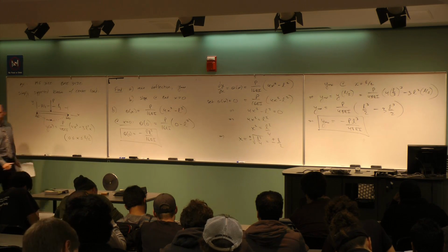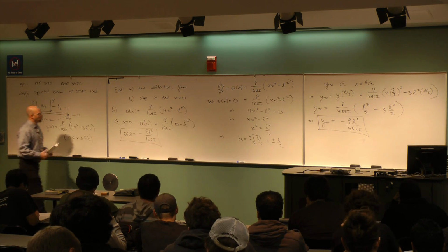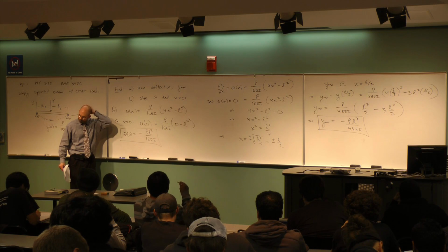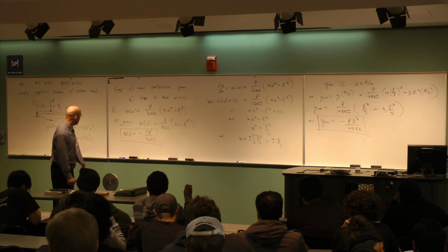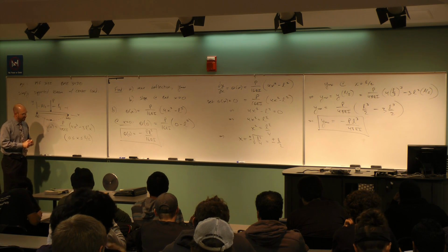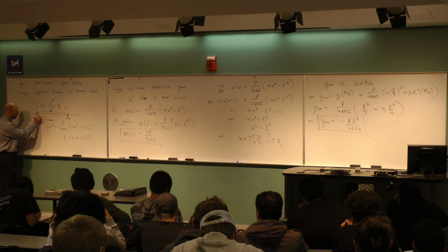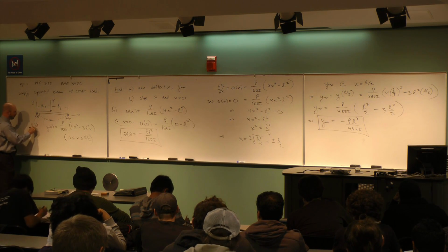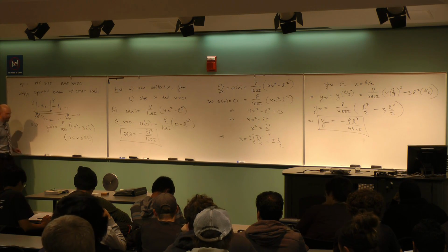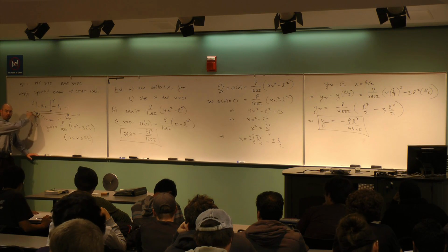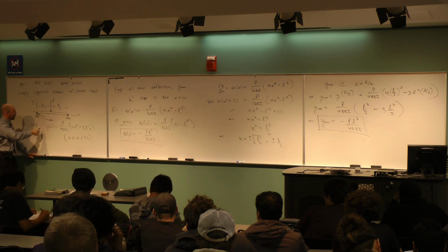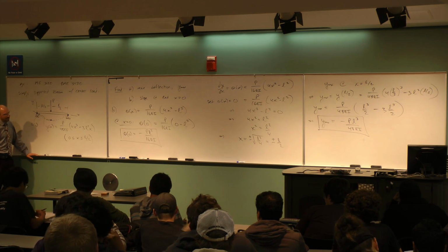By the way, how can I do a sanity check on whether or not the units are right on this? And also the sign, right? Does that negative sign make sense for this theta of 0, right here at the left end, this angle? Negative makes sense? Yeah, right? The slope is down. It's a negative angle because the y is up, so this is concave up. The y is up, the angle's down at the left end.